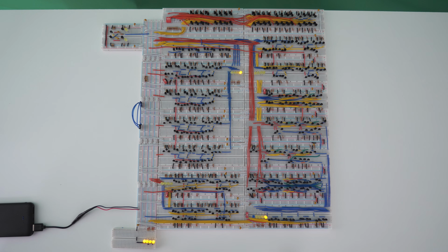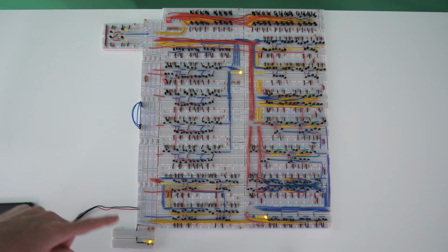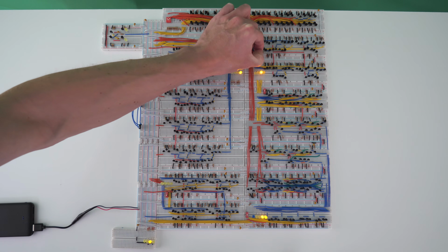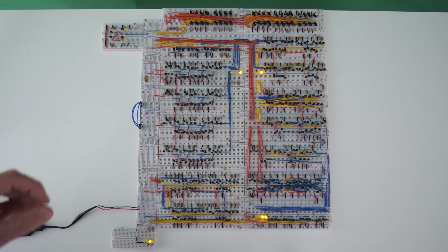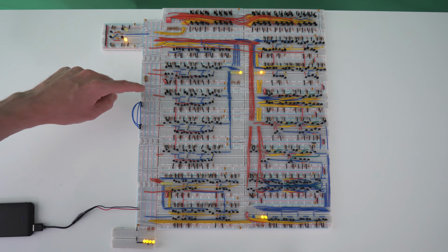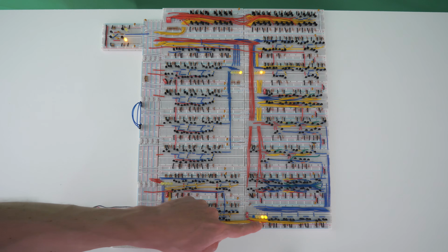The next thing we want to do is add 2. So we want to send 2 to the data bus, which we'll do by flipping this switch right here. Now we have a 2 on the data bus, and we want to send that to register B, which we can do by flipping this switch right here. So now we have a 2 in register B. We'll flip this switch so we no longer have data being sent from memory to the data bus. And now we have 1 plus 2 equals 3.